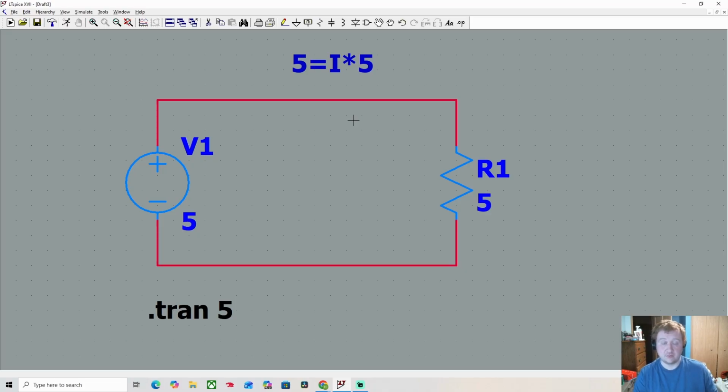So anyway, if I actually were to run this and show, oops, right, you need a path to ground. Now, up in the right hand corner, I'll also link a video on exactly what is ground. But usually you hook it up to the negative side of the battery or whatever power supply that you have, and then this will actually run.